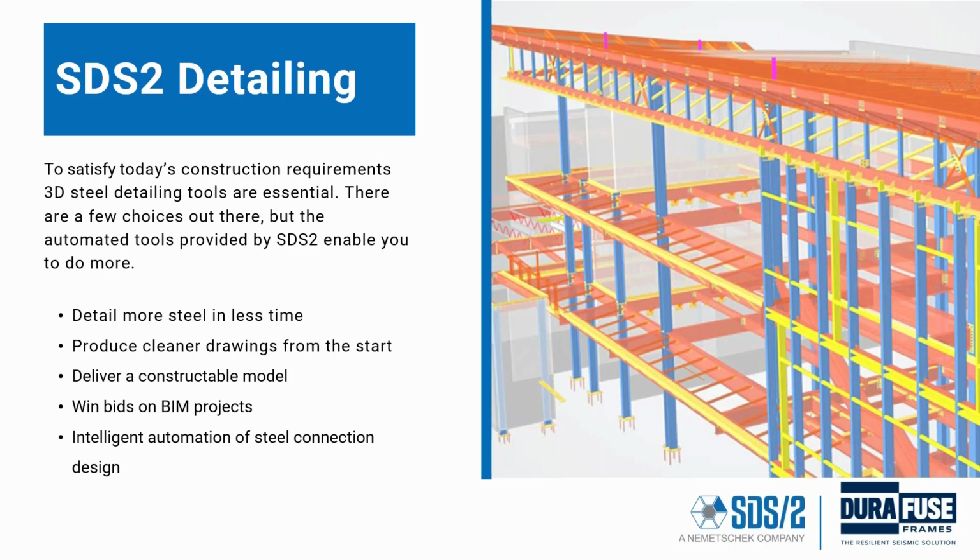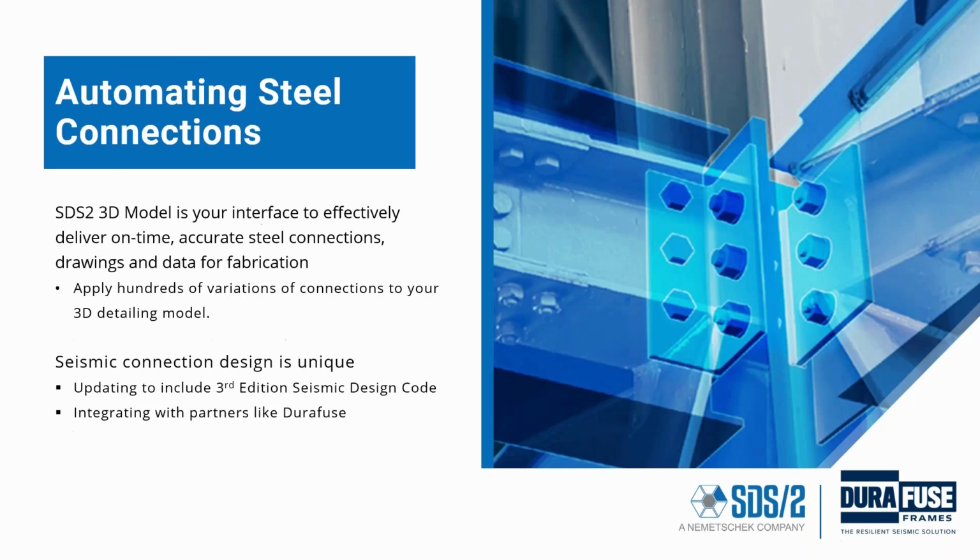But one of the things that makes SDS2 really different from everyone else is that we do this automation of steel connections. And when I talk about that, SDS2 inherently has hundreds of connection types that you can apply to your model through the connection design codes that we support. But when it comes to DuraFuse, they're dealing with more seismic connection design, which can be really unique. And we have some updates to SDS2 in 2021 that will include the 3rd edition seismic design code.